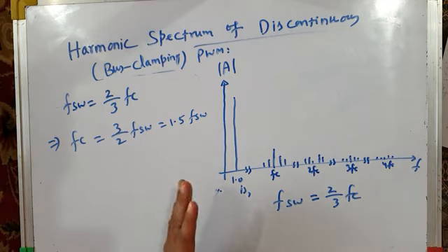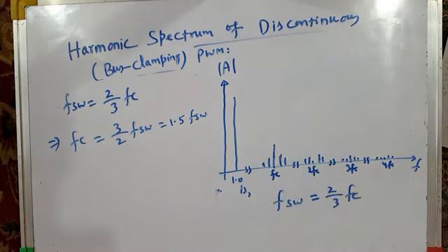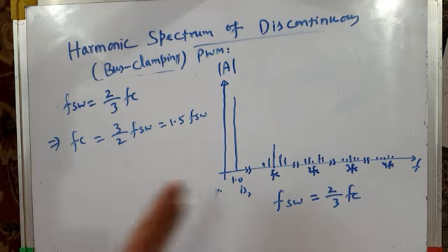But the harmonic spectrum slightly increases. I mean, this may be slightly higher than sine triangle PWM. Slightly higher, not much difference. If their THD is say 3%, here it may be 3.5% or 4%. There is slight deterioration of harmonic spectrum.